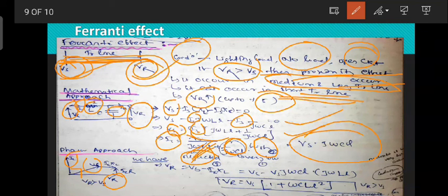And by this we will get IC XL and IC R. We have VR equal to Vs plus Ic into XL from this figure only. So by putting this equation in here, we get VR equal to Vs times (1 plus omega C L all square). So VR is greater than Vs here.